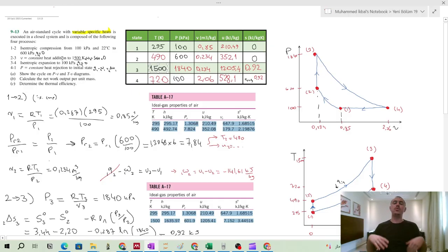After your combustion, basically in an engine, if you design a combustion chamber which resists high temperatures, let's say more than 2000 kelvins, what will happen? Will you increase the thermal efficiency? Actually, it is well known in engine design that the higher the temperature, the higher the efficiency. But we have some limitations for the materials and some other things, so we cannot exceed some temperatures. But we know that the higher the temperature, the higher the efficiency for gas power cycles. So we can see this effect by software, and we will do this.